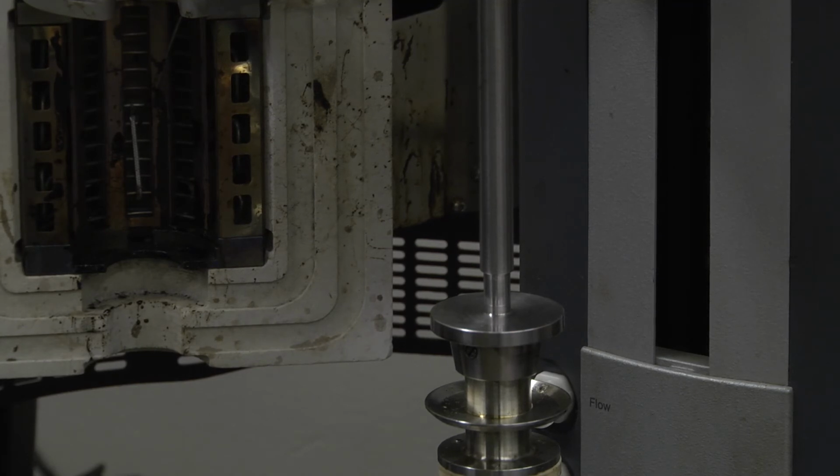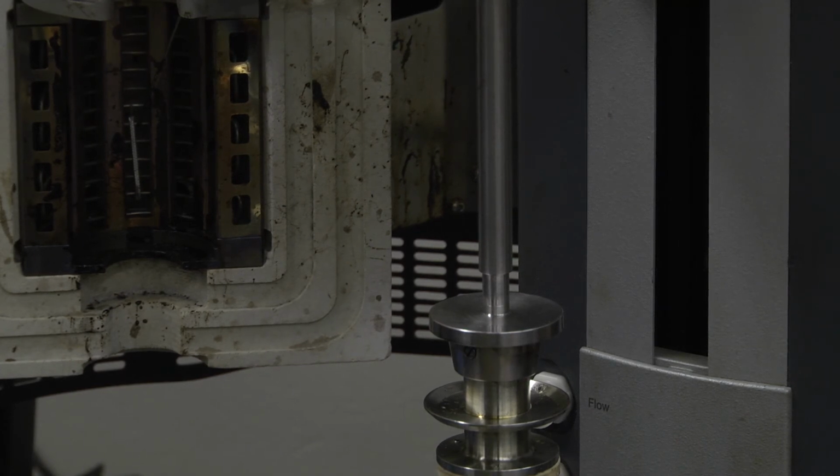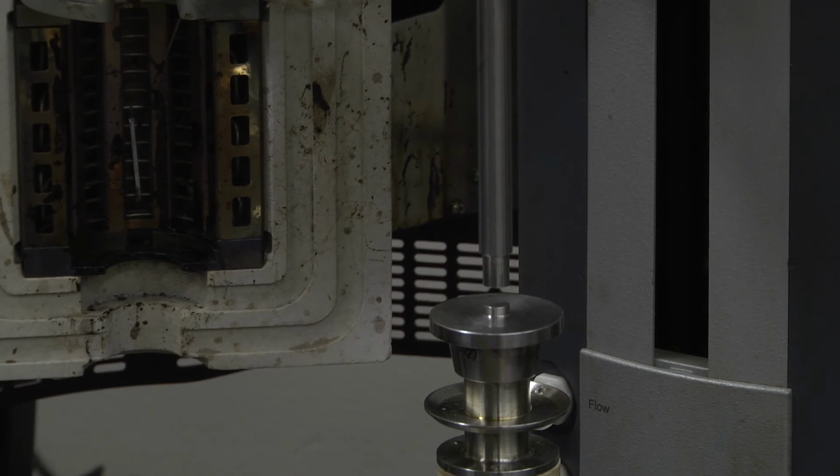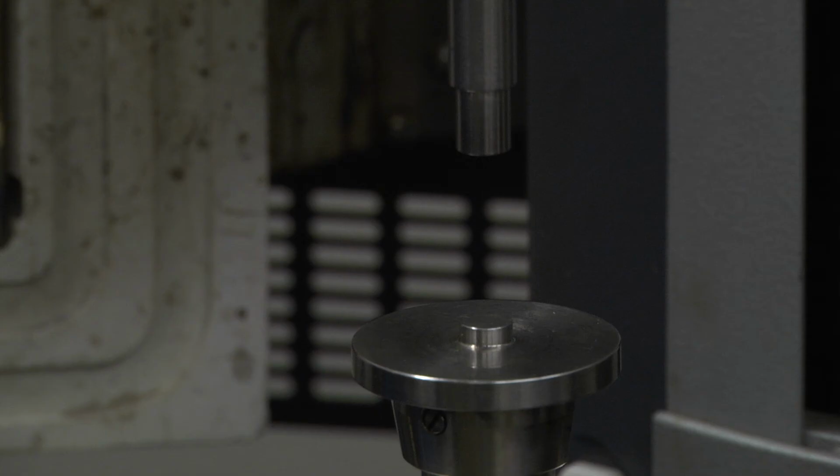In zeroing the gap, the spindle is brought down to the lower plate until contact is established. The instrument knows when contact is established as it registers a normal force between the compressing plates. The instrument then raises the upper plate until it records 0 normal force. This is the zero gap position where the upper and lower plates first meet.